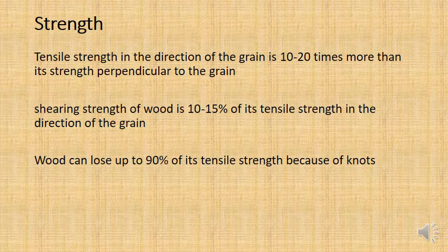So in terms of tensile strength, if you're trying to pull those grains out of one another, and so they're basically parallel, then the strength will be 10 to 20 times greater than if you were trying to pull the grains apart and the loading was perpendicular.